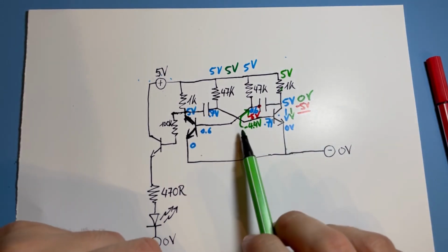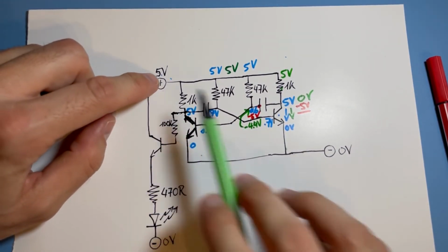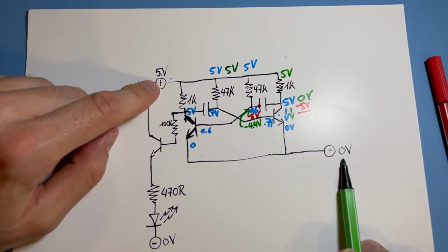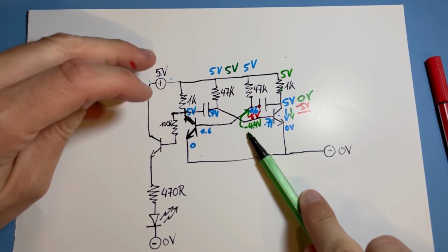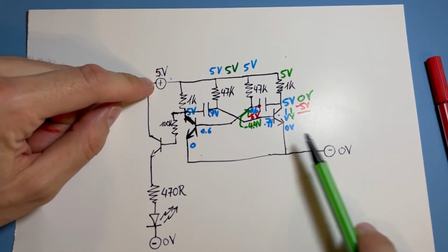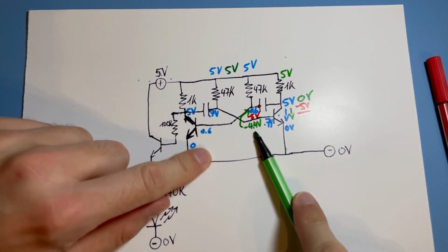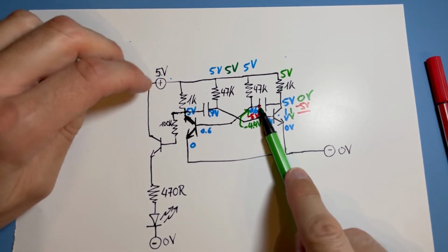And you couldn't imagine it because your whole circuit, you have supported it with 5 volt here and with 0 volt here, and you cannot imagine how something can ever be minus 4.4 volt. Seems impossible. That's not in our supply voltage. But it happens, and I tell you, I have watched it on the oscilloscope. It's really minus 4.4 volt on this side of the capacitor.